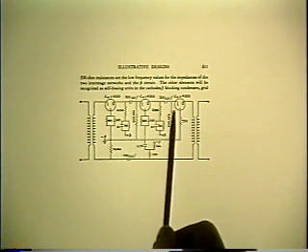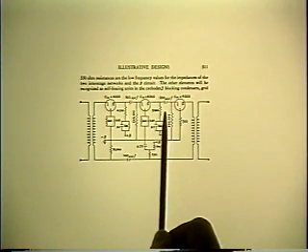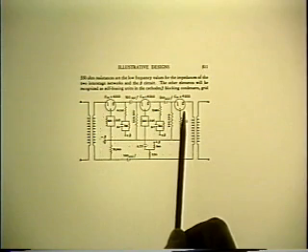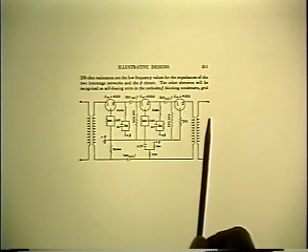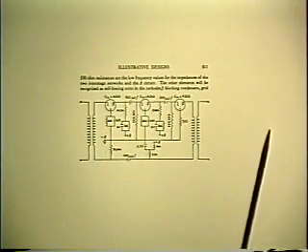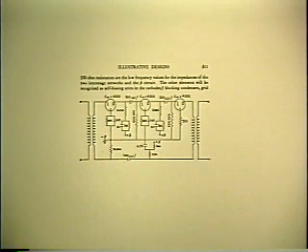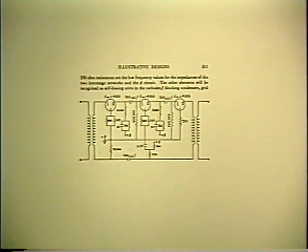Remember, in those days, the vacuum tube is the lousy thing, and you don't want to use any more of them than necessary. So certainly not more than 3. And since all of this is to go into repeater amplifiers for transmission lines that require matched impedances, what better way to do it than with a whole lot of transformers? So that's why the examples are mostly of this type.